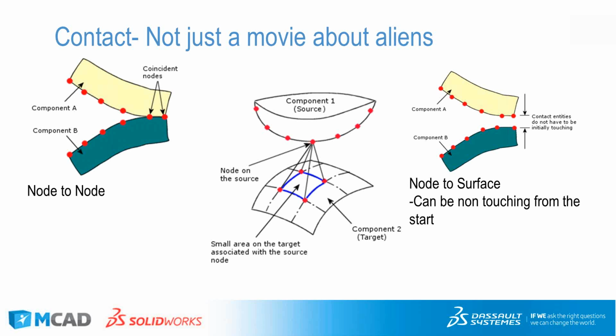But then you can go one step further, and in the SolidWorks menu there's the even more accurate form of contact, which I don't have a picture here for you, but it's surface to surface, where it literally engages the parametric equation that defines this surface, comes up with the XY coordinates of what that surface is, and then takes the other surface and sets them equal to each other and analyzes at the current geometry, is there anywhere that these faces have a coincidence or an intersection, and then it defines the contact. But asking a computer to constantly compare two very large and gross parametric equations obviously results in a pretty diminished capacity to solve quickly. Instead, you end up with lots of wasted computational effort looking at if surfaces are ever going to touch when you as the designer should have from the start known they weren't going to, so you don't tell them that they're going to, and you'll save tons of computational time.